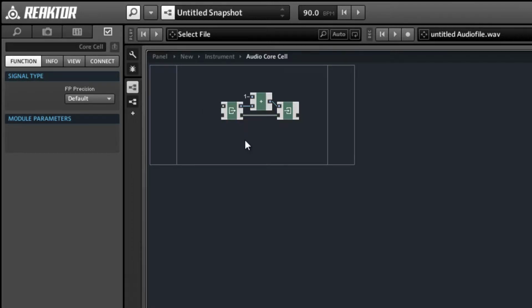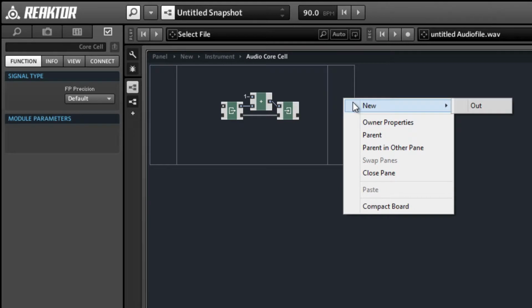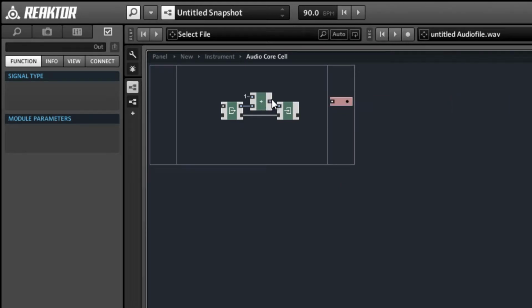So every time we receive an input at the clock of the read module, we're going to take the value we have stored, which defaults to 0. It'll start at 0, and we'll take that value and add 1 to it for each clock that we receive. That new value is then stored in the write module so that the next time we get a clock at the read module, it will be equal to 1, and then the next clock will be equal to 2, and so on and so forth.